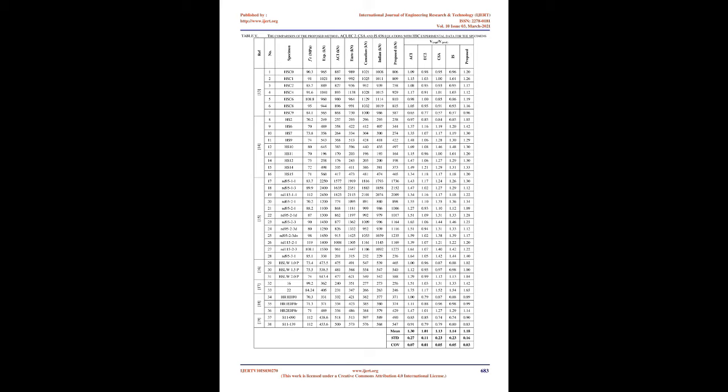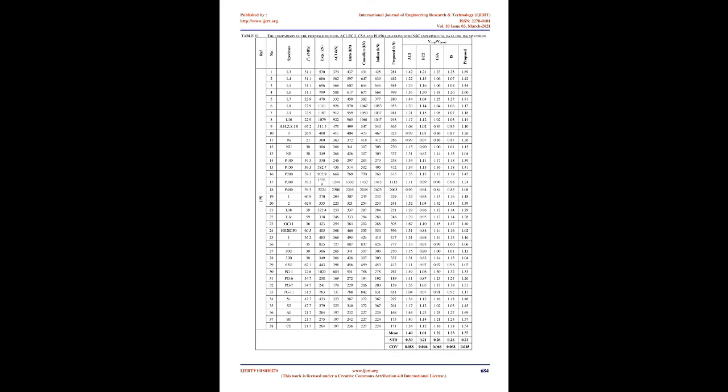The above suggested formula of equation was utilized to assess the concrete punching shear capacity for the 38 HSC specimens, and the ratios of the experimental to predicted punching shear capacity are then calculated and plotted as displayed in Figure 1. Comparison between experimental versus predicted by the proposed equation for high-strength concrete, HSC, specimens is presented in Figure 1. Although the basis in deriving the proposed equation was estimating the punching shear for high-strength concrete flat plates, we might extrapolate it for use with normal or low-strength concrete, NSC.